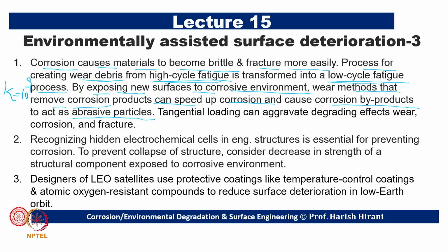That is why we say the wear coefficient in normal condition may be 10⁻⁹. Then when corrosion and wear get associated with each other, it turns out to be 10⁻⁶, and when corrosion, wear and fracture get associated with each other, quite possibly the wear coefficient may increase to 10⁻³, or 0.001 instead of 10⁻⁹. So, these are associated with each other. That is why we say these phenomena are important to understand, and in our earlier lecture we described those phenomena.